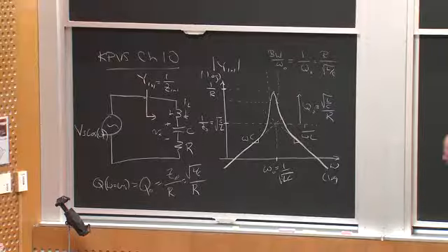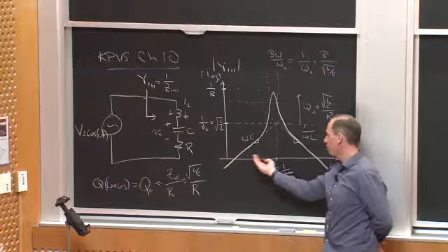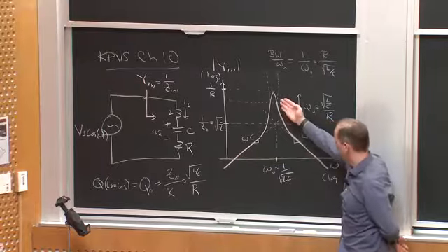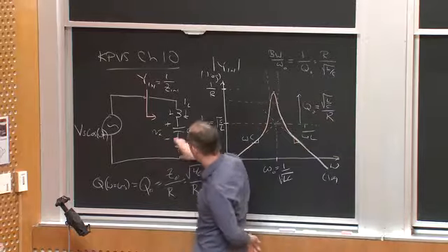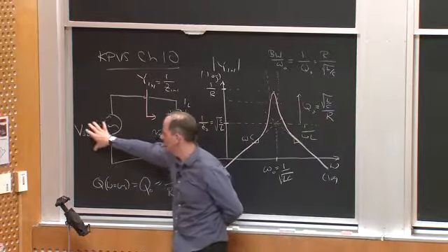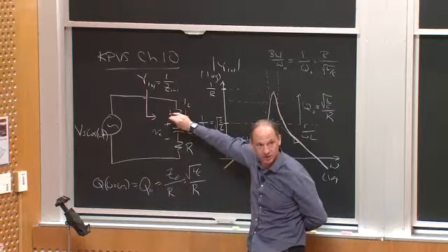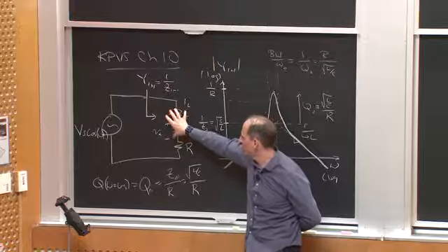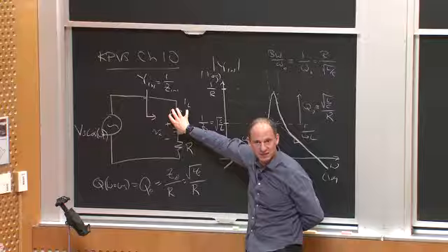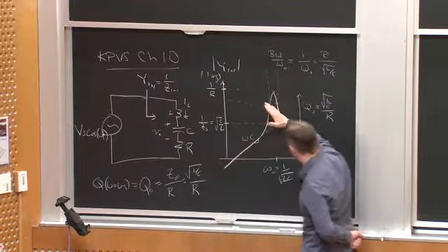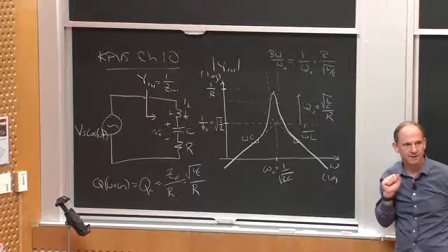Okay, so if we were to think about making an inverter, then by controlling frequency either above or below resonance, we can turn down the power, and when we're right at resonance, right, Vs appears across the resistor. So that's the maximum voltage I can generate in the resistor, because that's where the inductive and capacitive impedances are canceling. And at any other frequency, I'm going to have either a net effective inductive or capacitive reactance in series, so I get a voltage divider, my admittance goes down, and I deliver less power. Okay? Any questions about that?